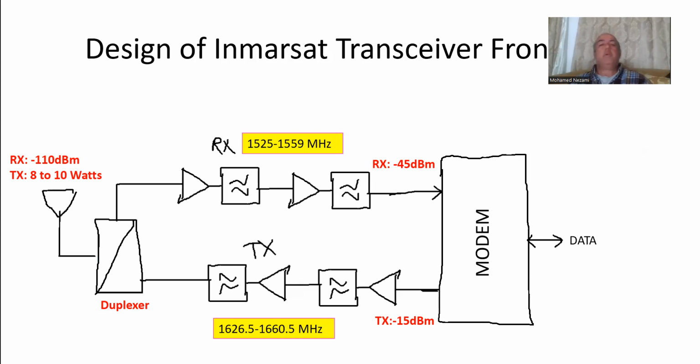That's where you take the board, import it into these design tools, and start cookie cutting pieces that are critical to this. So in today's design, I'm not using any discrete components. We're going to stick to MMICs basically, so everything is 50 ohm.